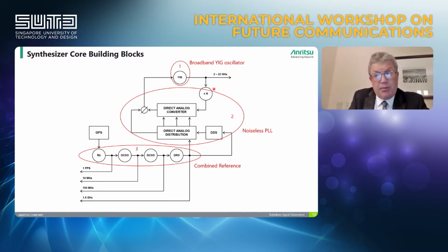A frequency multiplier works exactly opposite to a hypothetical frequency divider, meaning that instead of phase noise degradation, it brings phase noise improvements using the same 20 log n rule.